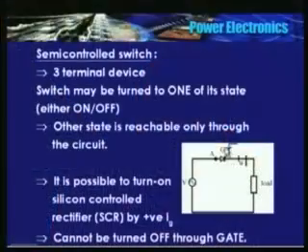In the case of a semi-controlled switch, it is a three terminal device. SCR could be one of the examples here. What is an SCR? I will tell you later. You can turn on this device by supplying a positive gate current when the device is forward biased.